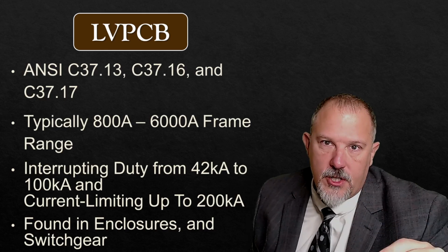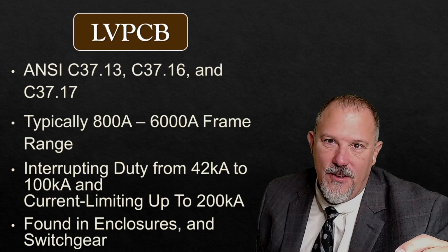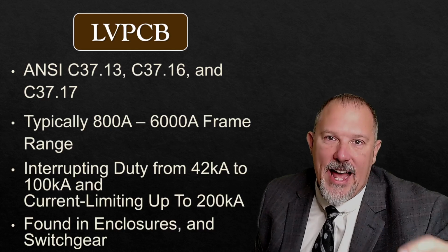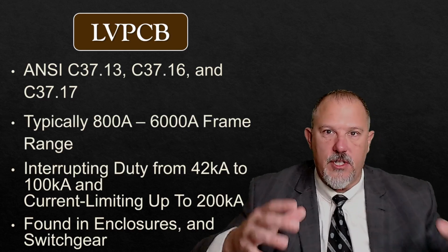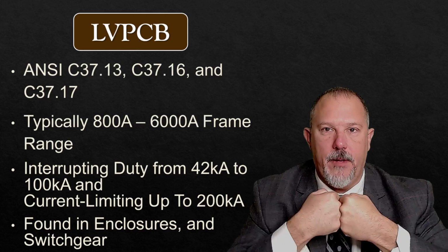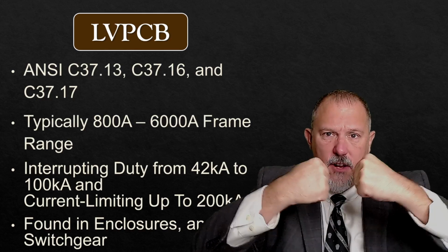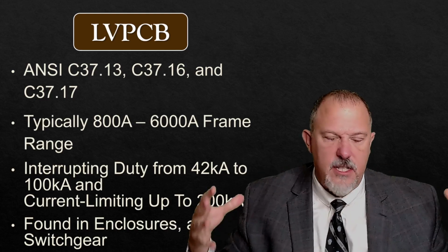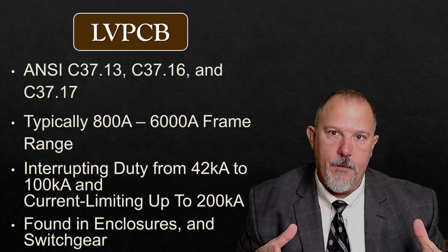A power circuit breaker is going to hold those contacts closed for up to half of a second. Think about the magnetic forces and the stresses on those contacts in that equipment. And how do I keep them closed? How do I make sure I have enough force? It's the springs, it's the beef I bring to the table. A low voltage power circuit breaker is a big boy.